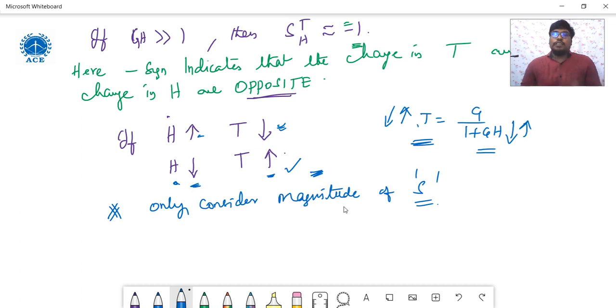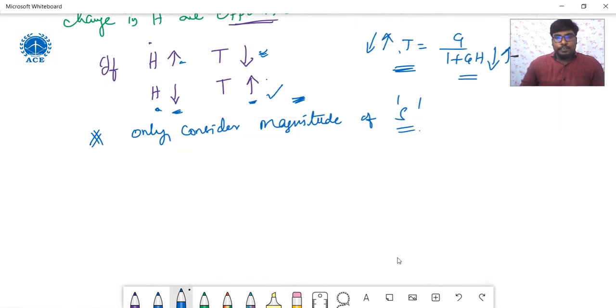Even though we get a complex value, we need to take its magnitude, because it is the ratio of change in overall gain divided by change in the parameter. So whatever change happens in the parameter, automatically changes will happen in the overall gain, right? So this is the sensitivity concept. In such a way, the effect of feedback will be taken on sensitivity.